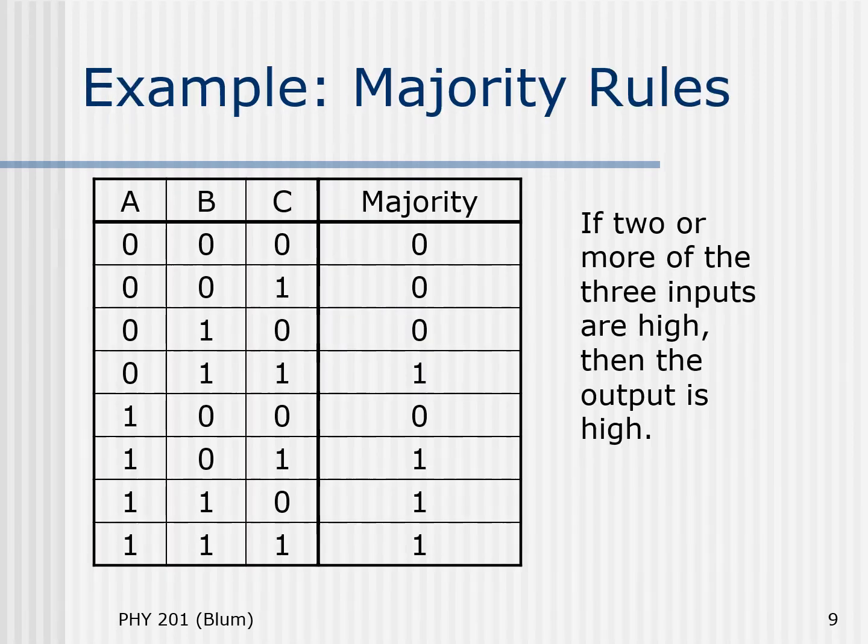So let's consider an example of majority rules. We will have 3 inputs, A, B, and C, and if 2 or more of those inputs are a 1, then we will get a 1 as an output. It's important that you realize that this is just an example, that the input side of the truth table, the A, B, C side, will always be the same. We have all 8 combinations spanning from 0 to 7 if we're using the counting technique. But the output side could change. It won't always be majority rules. We're just considering it to be majority rules for this example.